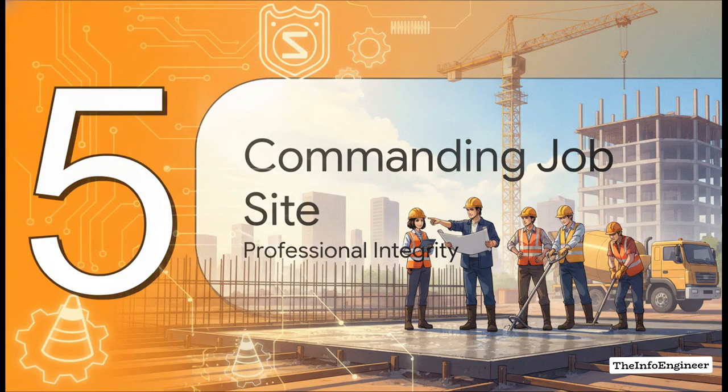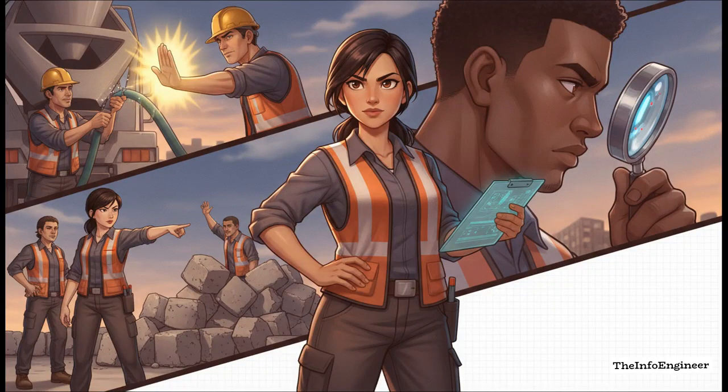All right, last section. Section 5, Commanding the Job Site. Professional integrity. These are your core field-hardened duties out there. You are the ultimate gatekeeper against unauthorized water. You use your visual examination of that slumped concrete as a highly powerful diagnostic tool to catch segregation early, long before it turns into honeycombing hidden inside a hardened column.